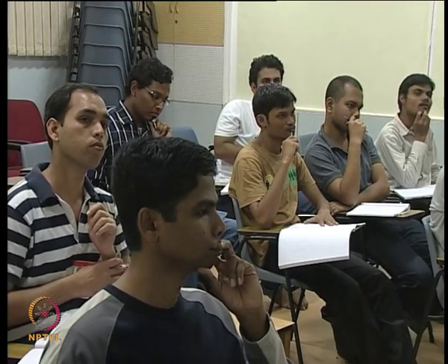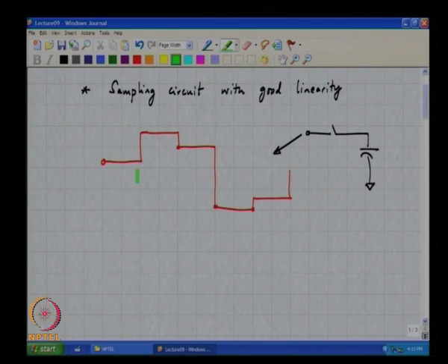Yeah. So, there is a crucial difference between this signal and the sinusoid, which is continuously varying, right. Within a clock period this input is constant, which means that if the resistance of the switch, even if it is nonlinear, is sufficiently small, what happens? At the end of the clock period, this voltage will be the same as this voltage, which means the derivative of the voltage is the same as the derivative of the input voltage, which means that the current flowing through the capacitor is